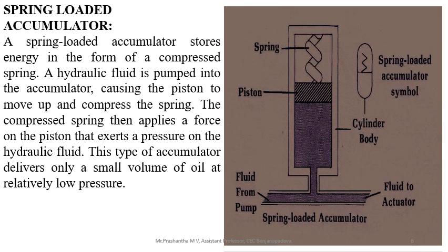Thus, the pressure exerted by the spring loaded type accumulator on the fluid is not constant as in the dead weight type. The advantages of spring loaded accumulators are they are easy to maintain, they are suitable for low pressure applications, and they are less expensive compared to weight loaded accumulators.